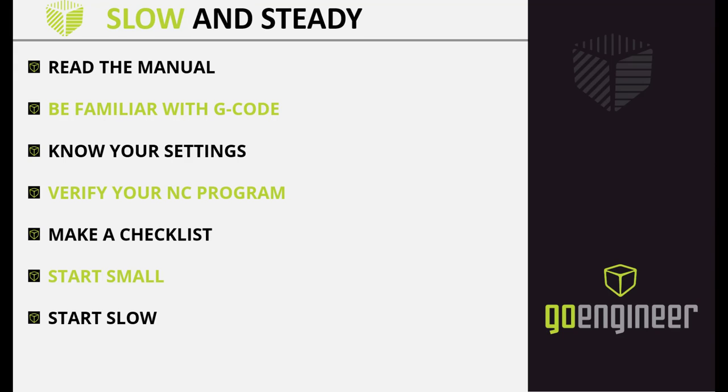First, read the manual for your machine. Next, read the manual for your machine. Yes, I did say it twice because it's very important that you know how your machine works. Be familiar with basic G-code commands. Review and verify the NC program to be sure it's accurate and to know what to expect from your machine as it runs the program.